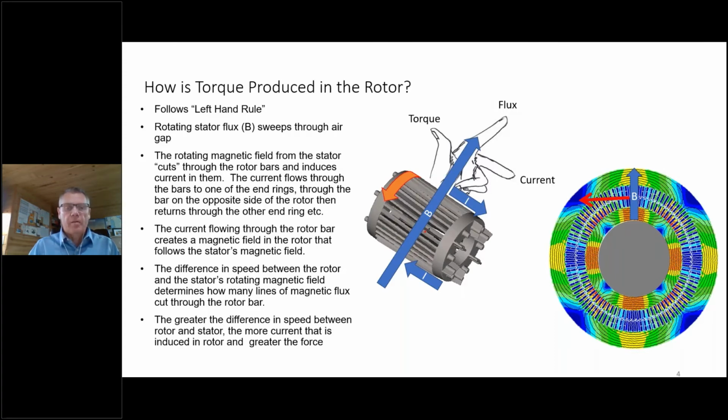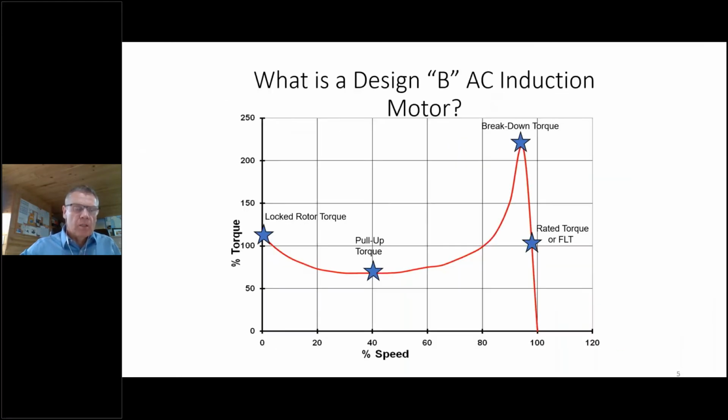The reason it turns is that, through AC current, the north and south poles of these electromagnets are alternating. So you start to get this cogging effect, and as you speed up, it becomes more and more smooth. Depending on the number of windings and slots, you can get a very, very smooth output. Like I said, that last slide was what they call the left-hand rule, and it talks about how you get flux and what's induced into a motor.